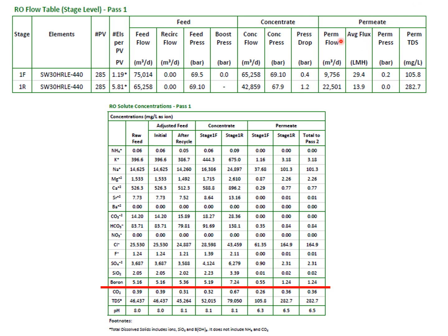Also permeate. So permeate flow, average water flux, and permeate pressure, and permeate TDS can be obtained. Also, we can see very detailed solute concentration. So already we input the different individual ions, ammonia, magnesium, barium, carbonate, bicarbonate, chloride, sodium, boron.